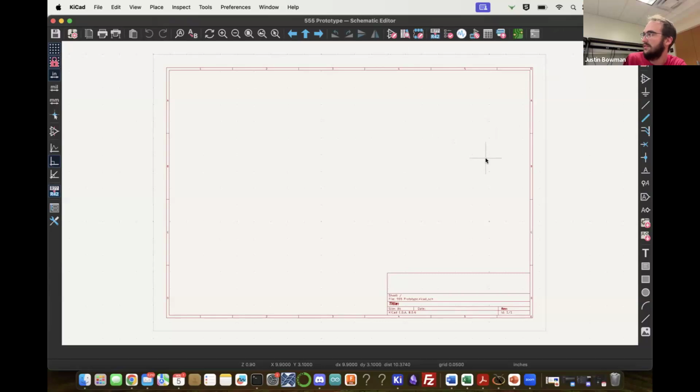Yes, what is actually going to be on the board itself. Right. So the first step is to do the schematic first. It's basically converting from your hand-drawn system that you want to design, and deciding, all right, this 555 timer, what does it connect to?